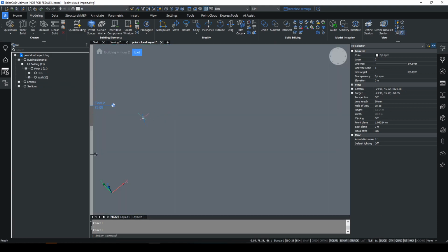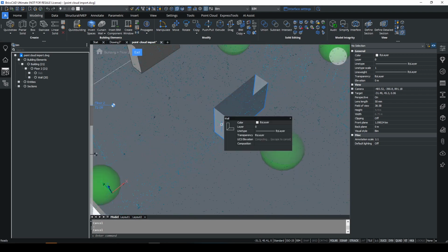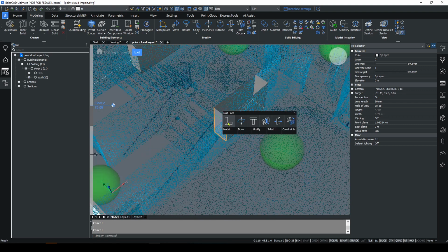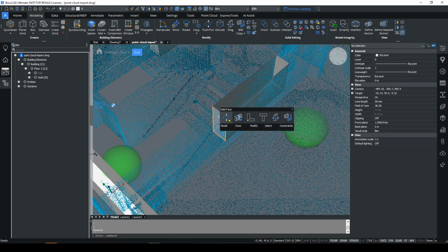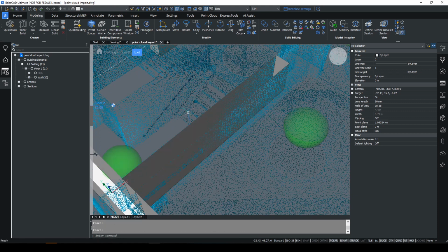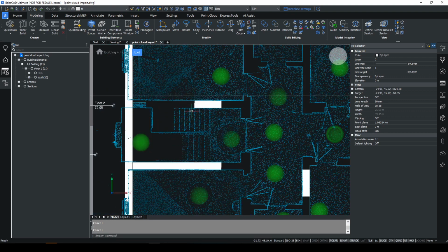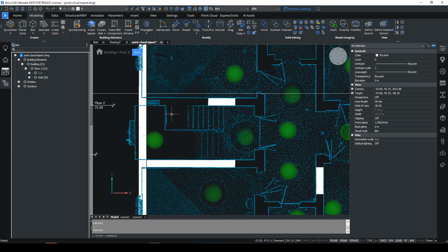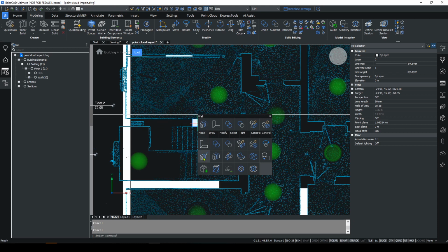Previously what we would do here is go to a 3D view and click on the area of interest, and you could either use the push-pull command, or you could use the connect with nearest wall command on the face. That works quite well, but everybody wants to work in plan views these days. So the way we have fixed this in V23.2 is we've got new commands called BIM trim, BIM extend, and BIM slice, and these do exactly what you'd expect.